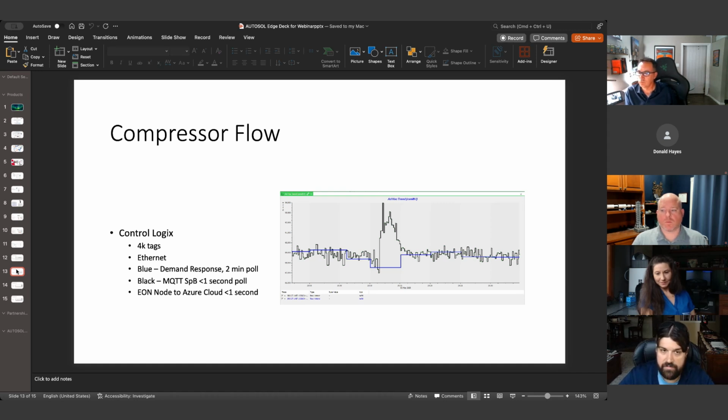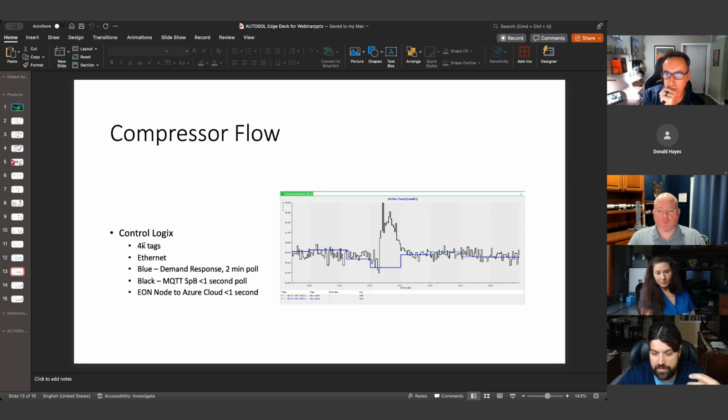And then we can use that high fidelity data to do comparisons over time. Maybe if there is a spike, where traditionally in the control paradigm we would say, okay, if the pressure hits above this number, we know that there's an issue. It's a very one-dimensional way of addressing things, and customers are realizing that maybe that pressure point at that point in time is not actually as much of an issue as we would have thought. We're worried about whether that pressure during that peak is trending over time, not just a given one-dimensional thing, but very much three-dimensional: the data point, the cycle that it's in, and the period of time.